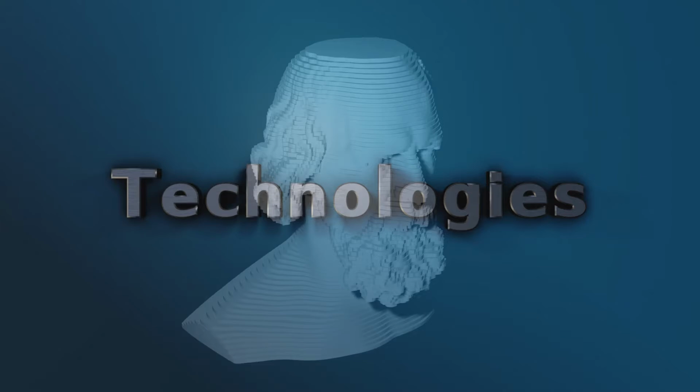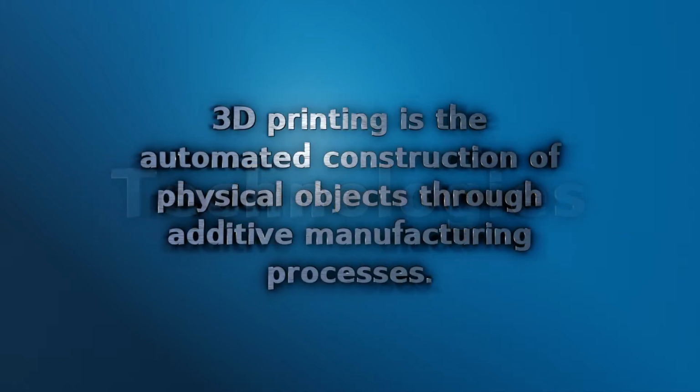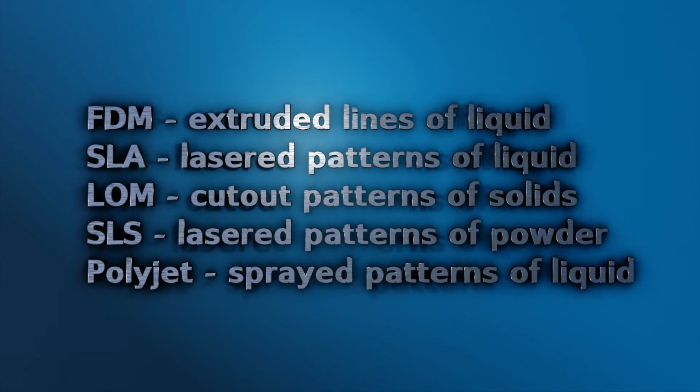There are many different rapid prototyping technologies and processes in use today, but they all fall into one of two major categories: additive or subtractive. Subtractive manufacturing is any process where material is removed to create something. True 3D printers are additive devices that combine many layers of plastic, resin, metal, or many other materials to construct complex shapes. Some of the most common of these approaches in the 3D printing marketplace include FDM, SLA, LOM, SLS, and PolyJet.